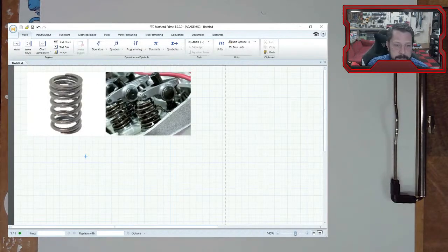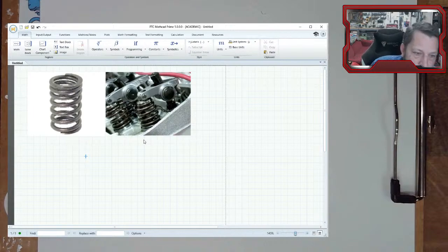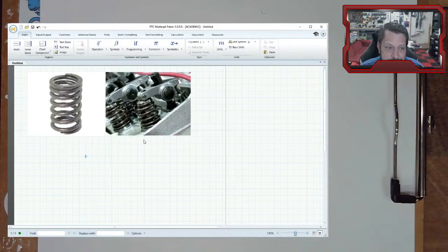Yeah. So here's a couple of coil springs that would be in like a valve train for an engine. Now the ones in the picture over here, you can kind of see they're a little bit tapered. This first coil is a little bit smaller than the others, so they have a little bit of variable frequency or variable spring rate to them. We're thinking more of one like this, where all the coils are the same diameter, and this one would be closed and ground. You can see how that last coil on the top and bottom of it have been closed over, and then it's ground flat. So this would be closed and ground and a compression spring.